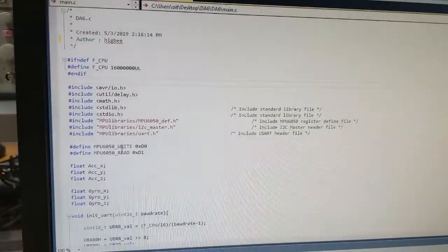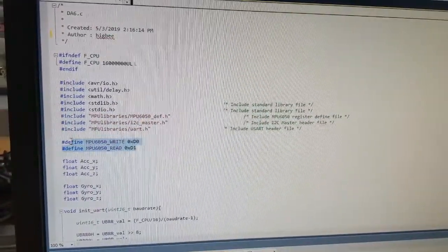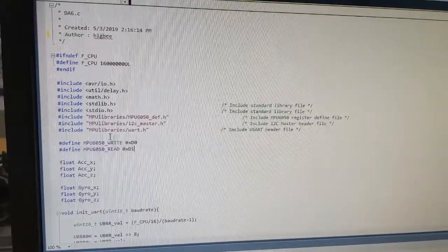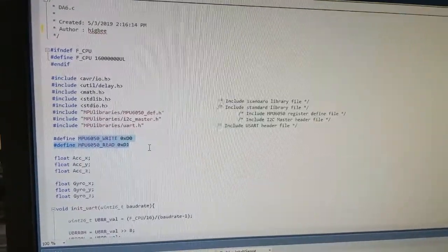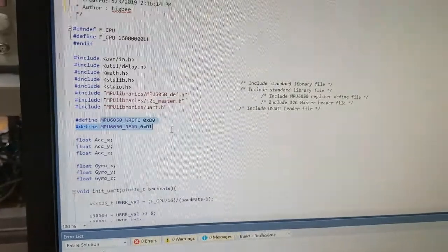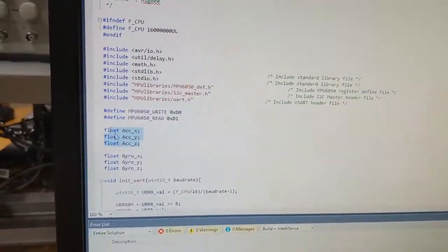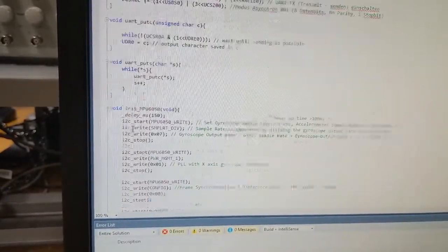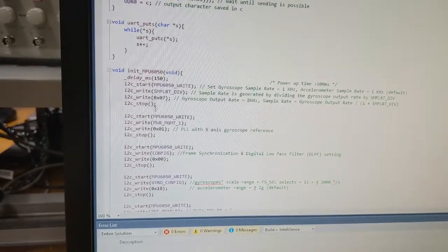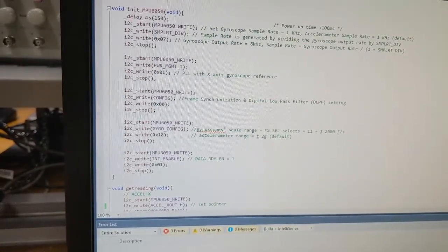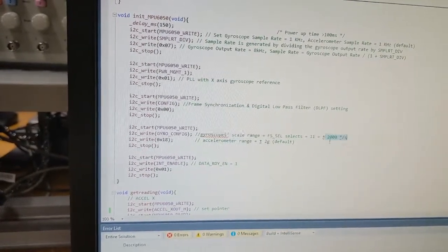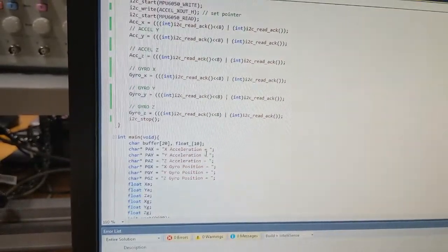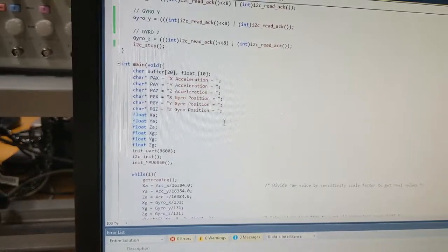Okay, going to the main C code, using those libraries and using these commands over serial communication. Basically, as we change these values over the synchronized clock cycle between the two devices, we get commands out. I want to go to the main. So there's initialization, writing, setting up the configuration of these registers, setting up the ranges between 2Gs or 2000, depending on which one you're looking at, and that will end up determining the value that you use for some of these conversions later as well, right here.